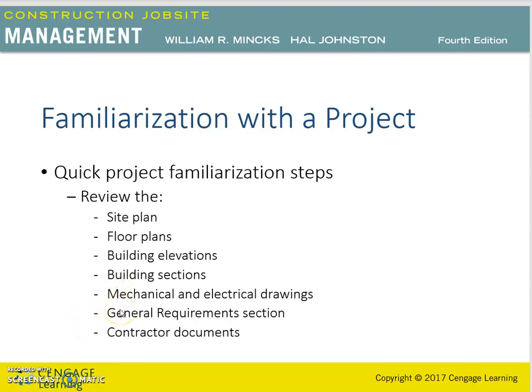Then the mechanical and electrical drawings should be reviewed to determine an overview of the involvement of both areas in the construction. The general requirements sections of the specifications should be reviewed, determining the special circumstances for the project and the completion date of the project.